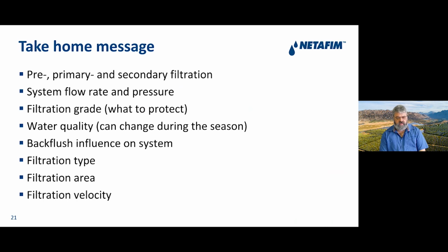Water quality, the most important is to understand what is the water quality that we work with and how it changes during the season. And obviously we must design the system for the worst case scenario. Backflush influence on the system that we discussed. Are we allowed to influence the system during backflush or not? And that will also influence our design.